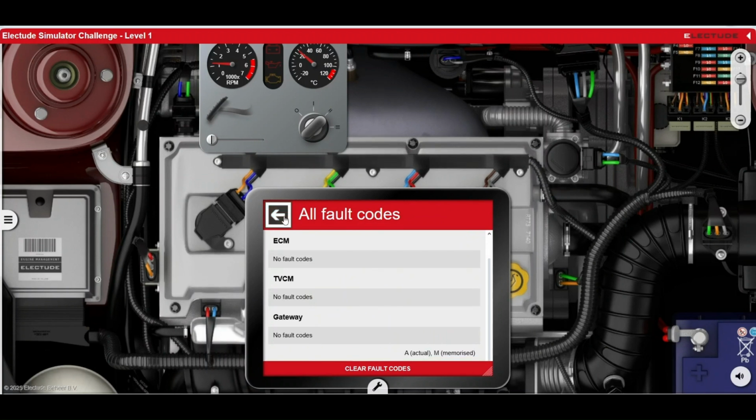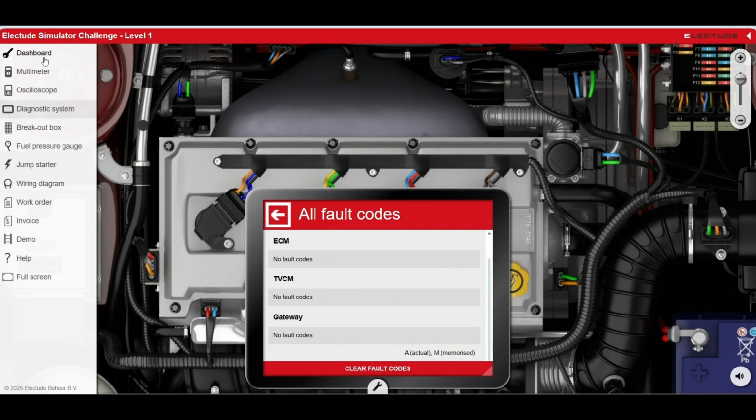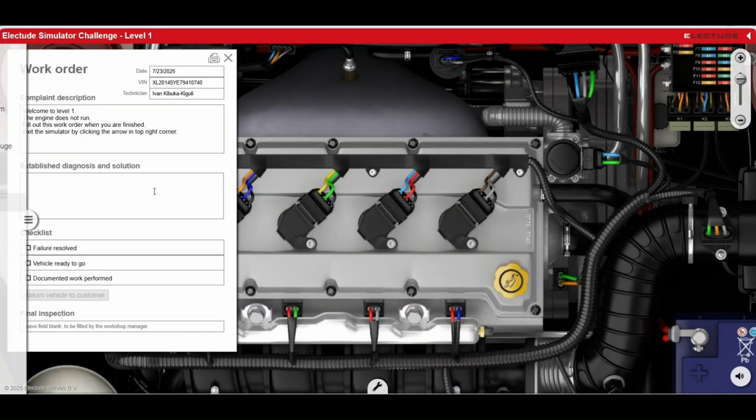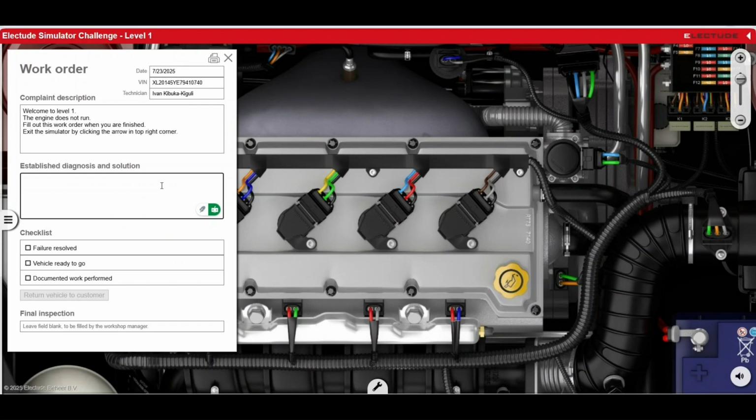Remember, it had more than 10 fault codes, which have all disappeared with just one fix. So it's useful to keep a sober mind and make sure you are not diverted by the number or description of fault codes. The description can be important, but the number, sometimes you need to realize that not so many components can break down on the same car at the same moment.